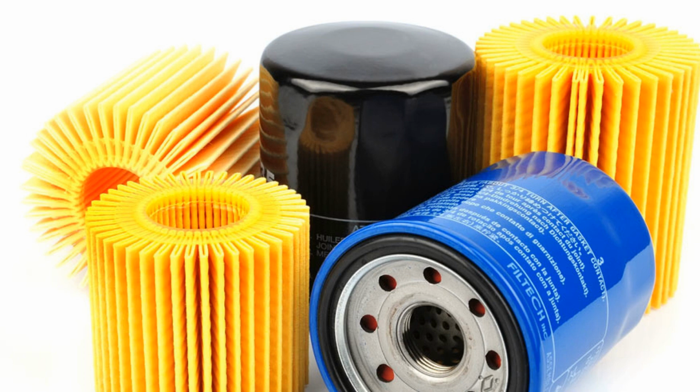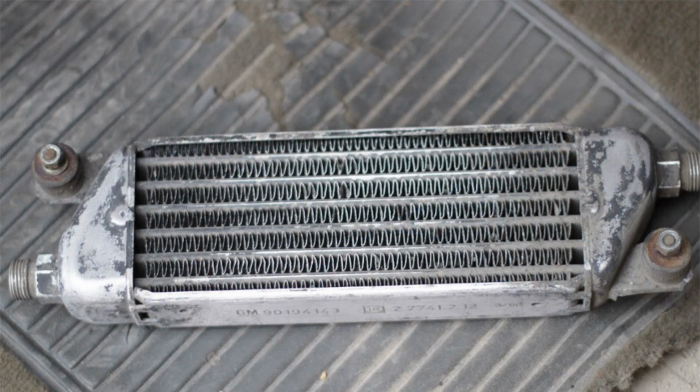Let us enumerate the list of tasks solved through the use of the lubrication system. Reduction of friction force due to formation of the thinnest protective film on the rubbing surfaces, cooling of surfaces of power unit parts, cleaning of technical fluid on the protected surfaces from metal chips and other solid contaminants, ensuring uninterrupted circulation of lubricating fluid at the required pressure, prevention of premature wear of engine parts.